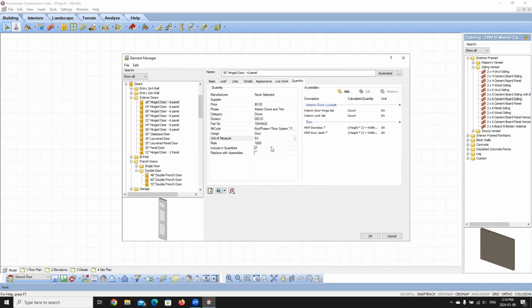Most elements in the catalog will have a mark option, so you can actually go in and apply a mark to the element itself. If you add something in here, it will include that mark in the drawing. So right now we're adding in a door, so we're going to see that mark of 16, so 1'6" by 6'8", which is basically just telling us the size of the door itself. You can have that set as a typing field. You can also set it to be off or auto or custom, and you can adjust again however you want that to be defined.